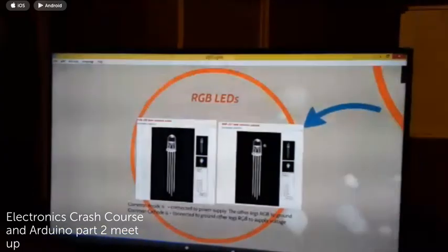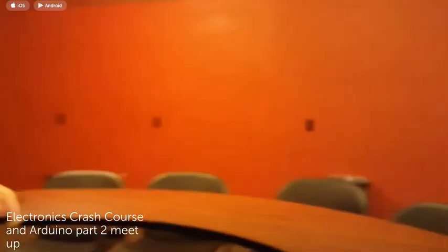you got to do. In fact, not to confuse anybody, you can even take that part that's the common cathode that would go to ground, and you could actually hide the resistor in there, because as long as it's somewhere in the circuit to limit that current, you're good. Yes. But if you want to have total control of the Arduino board, which of these two would you use?